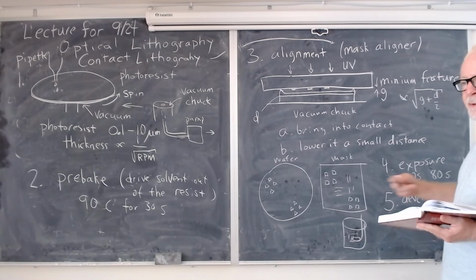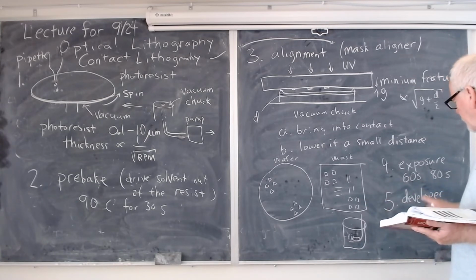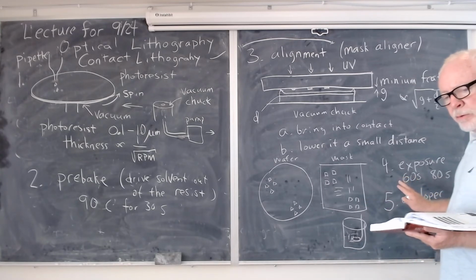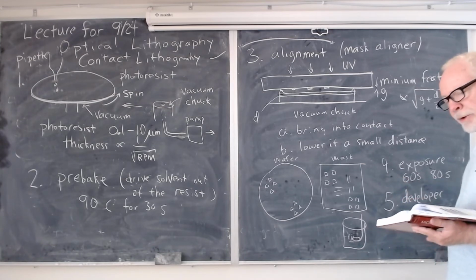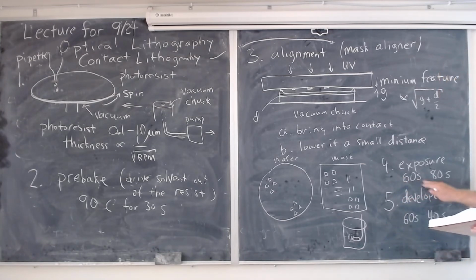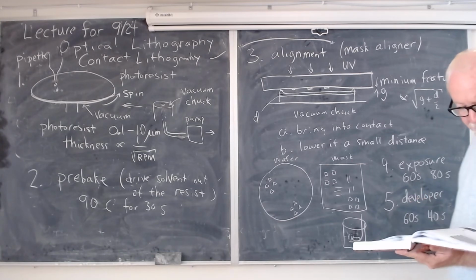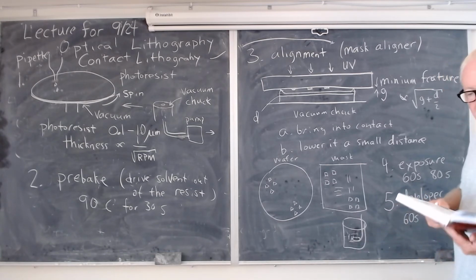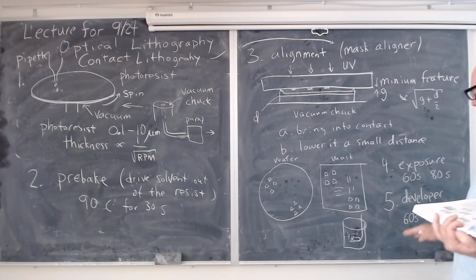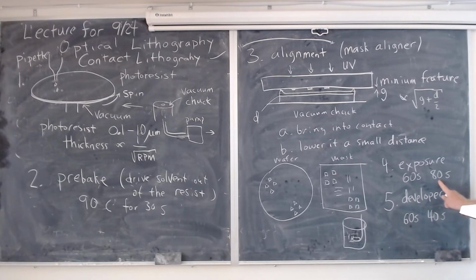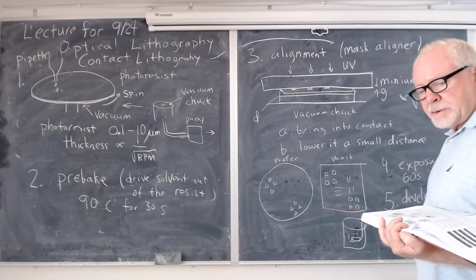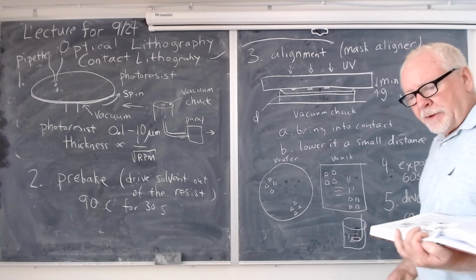and you quickly find out, for whatever photoresist you're using and the type of process you're doing, how important it is to get an exact number on either of these things. But basically, if you overexpose, you correct it. Now, the thing is that, number one, if this is the proper design for the process and you accidentally expose too long, it'll develop faster. And what happens is that your features can get too big, because your development goes too fast.